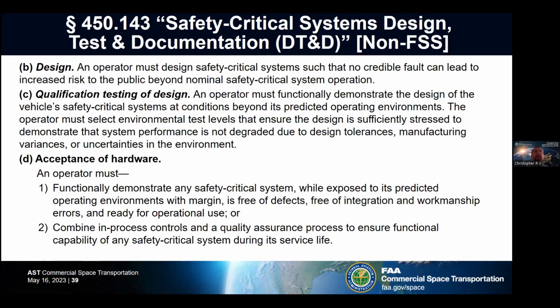And those environmental test levels must ensure that the design is sufficiently stressed to demonstrate that system performance is not degraded during operation. Acceptance of hardware, 143D. An operator must functionally demonstrate any safety critical system while exposed to its predicted operating environments with margin is free of defects, free of integration and workmanship errors, and ready for operational use. And the operator must combine in-process controls and quality assurance processes to ensure functional capability of any safety critical system during its life cycle, service life.